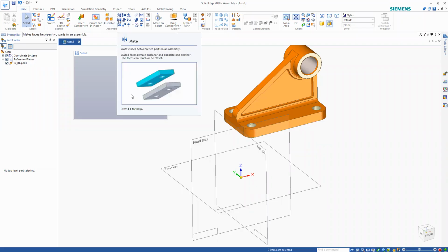Maybe if I say, for example, mate, and then you can say align. You see here, right? The animation, align. Now if you go to mate, you see what's going to happen. You identify the difference? Align is, if you have a surface normal, right? Normal pointing outwards.